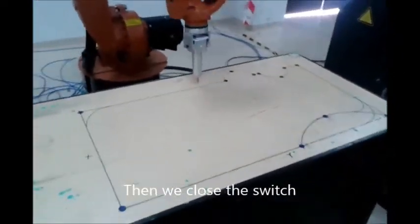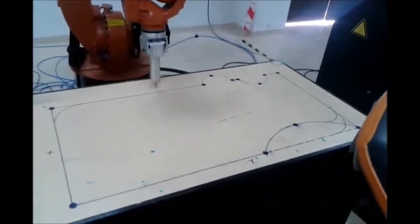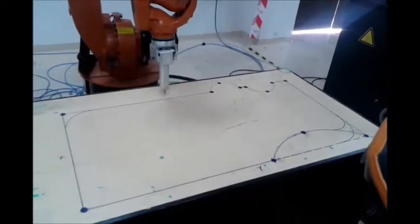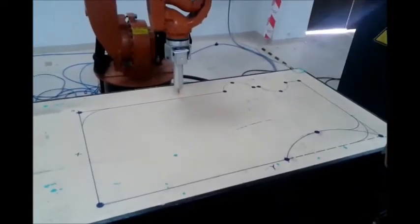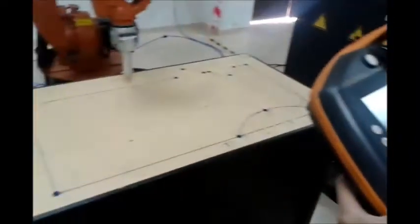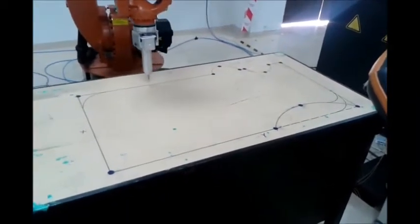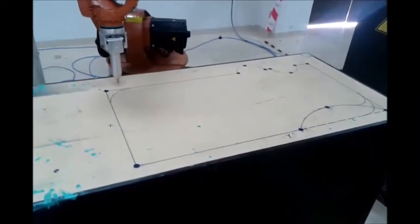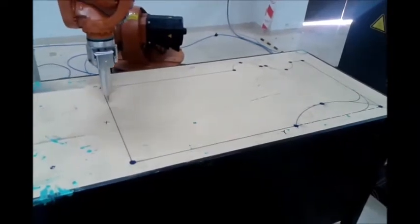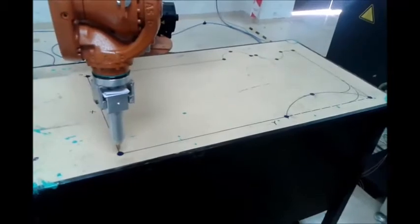Just now it already passed through the out function, meaning the LED light over there turned on and off already. At this moment, the sing out function has also activated, and the LED light 13 there also turned on already. When the robot goes to the final point, this is the point where we set sing out to switch off the light. So that's all for our program.